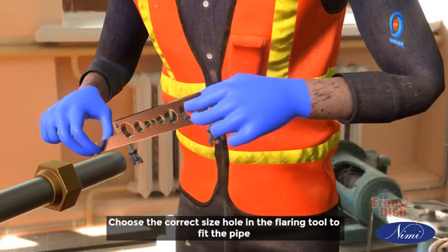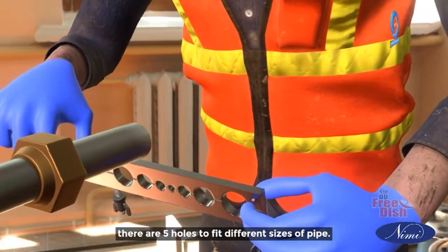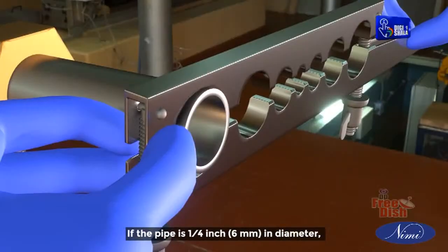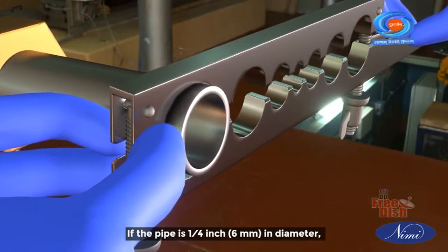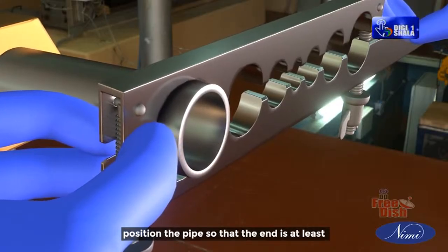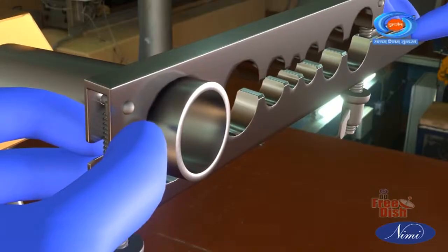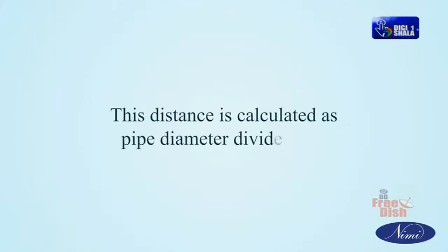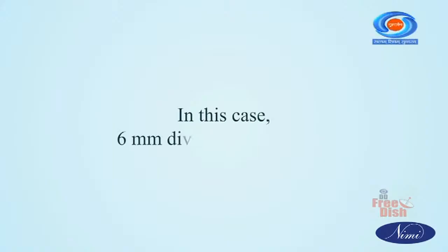Choose the correct size hole in the flaring tool to fit the pipe. There are 5 holes to fit different sizes of pipe. If the pipe is 1/4 inch, 6 mm in diameter, position the pipe so that the end is at least 2 mm above the top of the flaring block. This distance is calculated as pipe diameter divided by 3. In this case, 6 mm divided by 3 is equal to 2 mm.